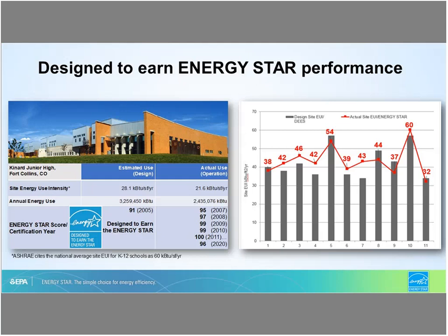And what it does is provide information so that once you have your design, and in most of the cases the design EUIs were lower than the operational, it provides a metric for you to understand what the design intent is and what activities you need to do to get the building to achieve its operational performance by calibrating systems and making them work in conjunction with the occupants' needs.